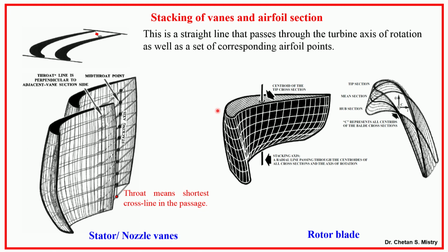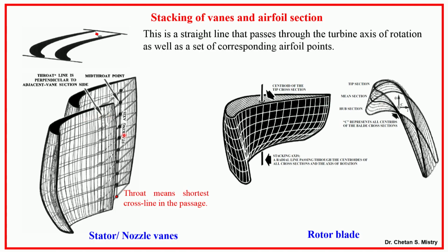Next, after the design, we are talking about the stacking of my blade. Say I have a number of aerofoils. There are two different possibilities for the stacking. If we are talking about the rotor, all my blades are stacked by CG, and that is how I will have a twisted blade. Similarly, if I need to have a constant nozzle angle, then what we need to do is calculate the mid section of the exit passage, and based on that we need to stack.